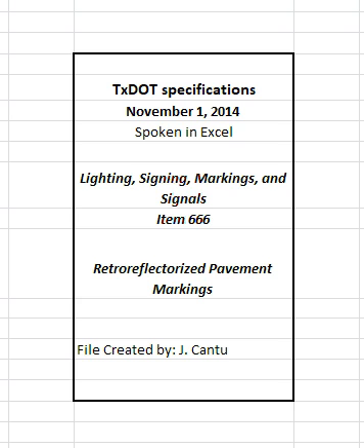The transverse width of the profile must not be less than 3.25 inches, and the longitudinal width not less than 1 inch, when measured at the top surface plane of the profile bar. The profile may be either a 1 or 2 transverse bar profile. When the 2 transverse bar profile is used, the spacing between the bases of the profile bars must not exceed 0.50 inches. The above transverse bar width is for each 4 inches of line width.